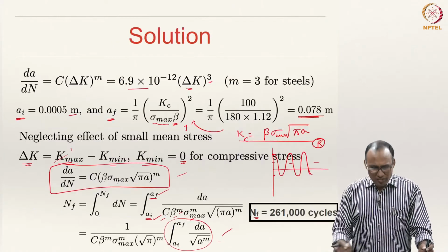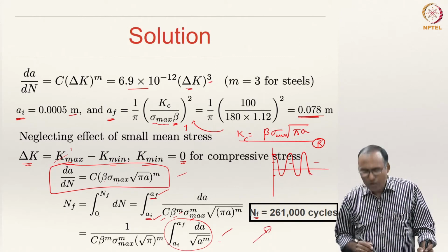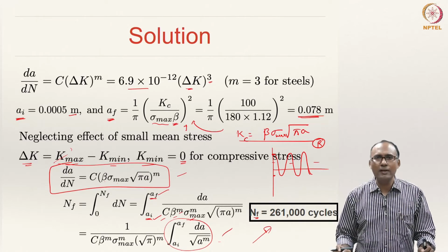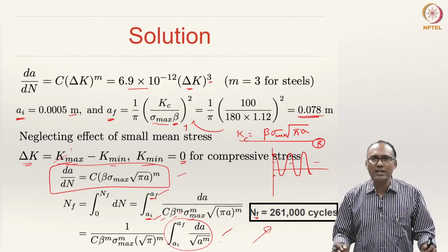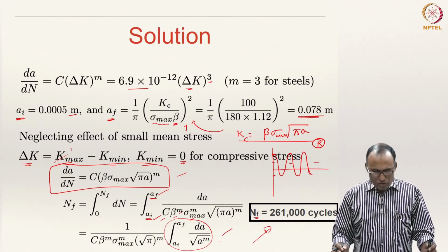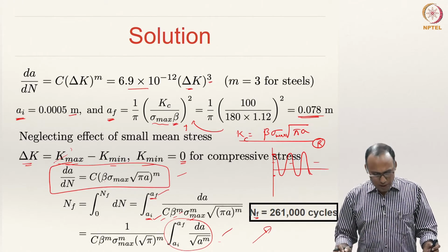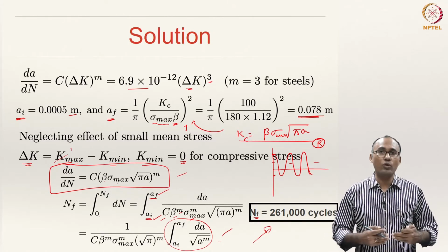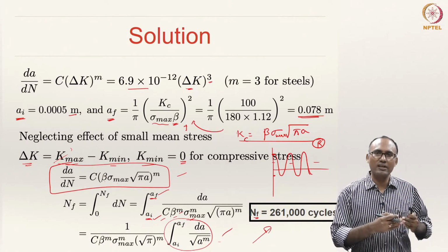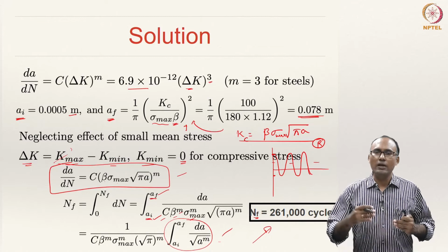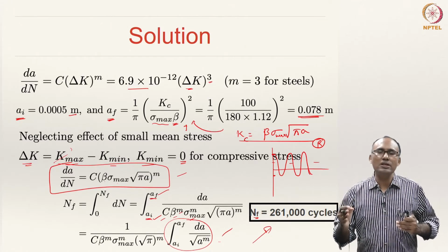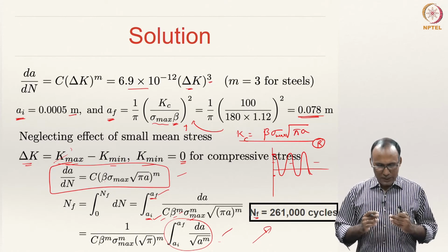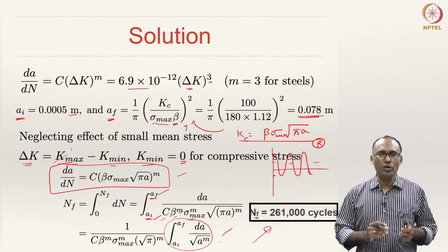Okay. So, this is how one would be able to calculate the remaining life of a component by knowing the initial crack size and other properties of the material, together with the type of loading that can be applied to the system. So, with that we have understood how to go about calculating the remaining life from the fatigue crack growth point of view. That means you have an initial crack and you are letting the crack grow, and what is the limit up to which you can continue to use the system, right. All right. So, with that we sort of close this module on fatigue failure theories.